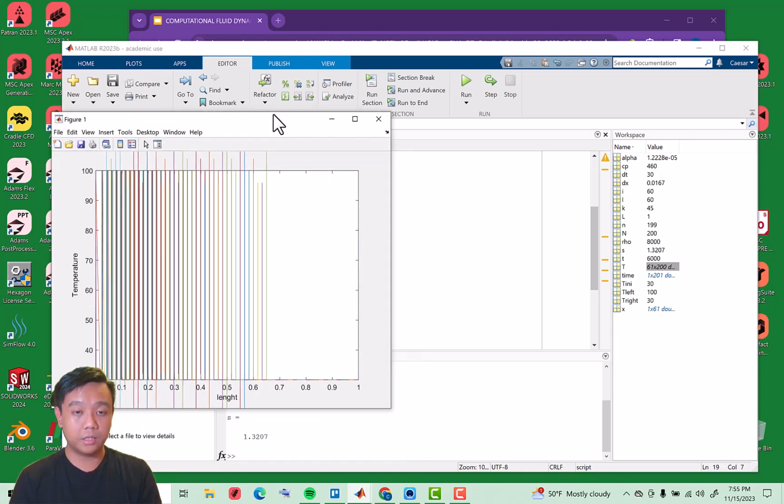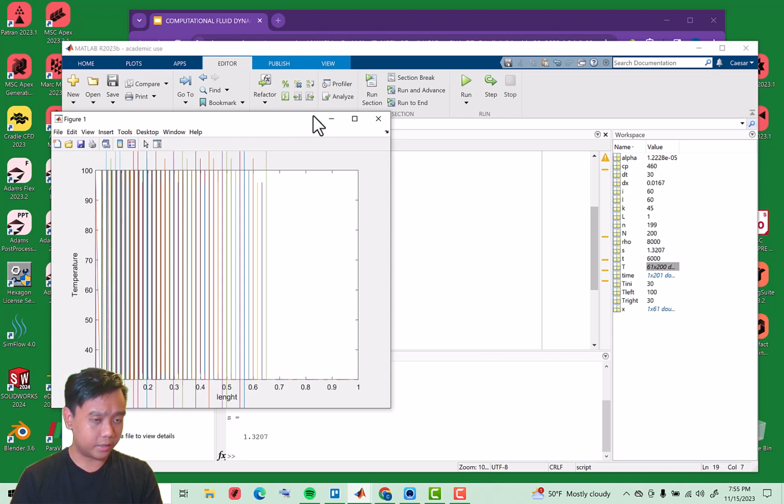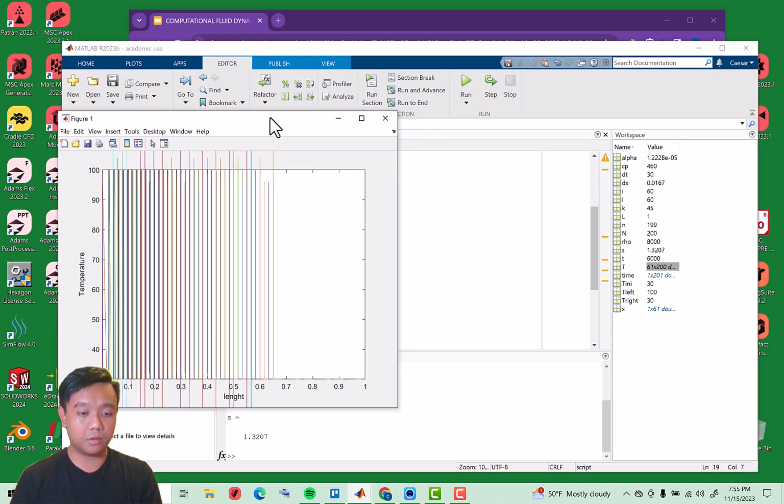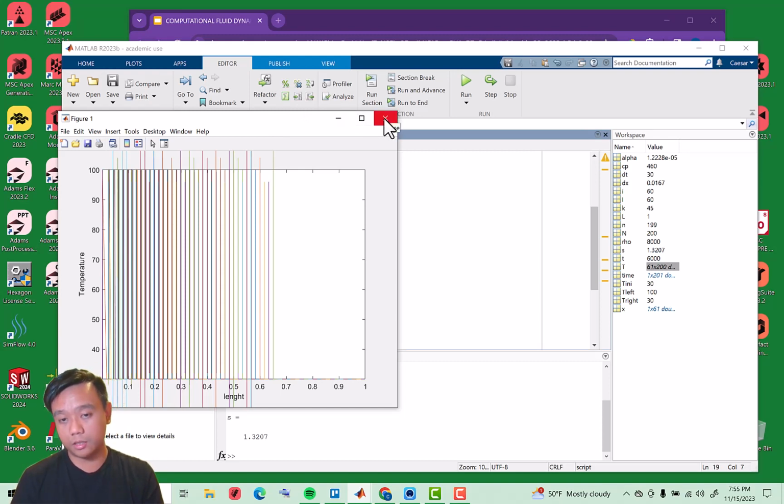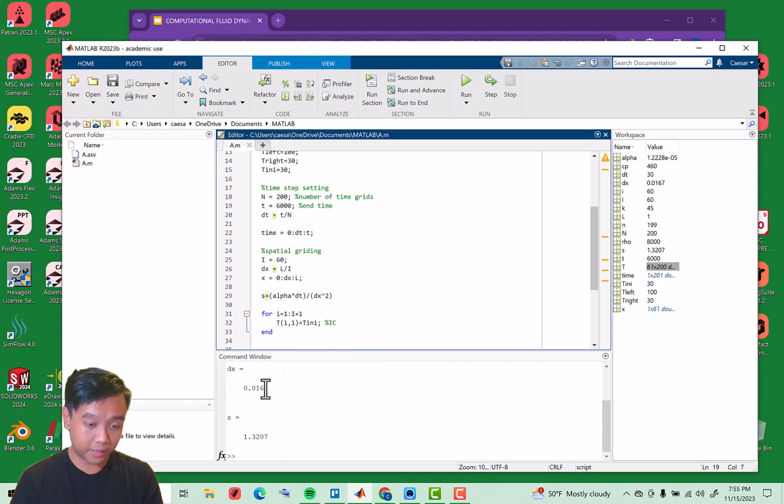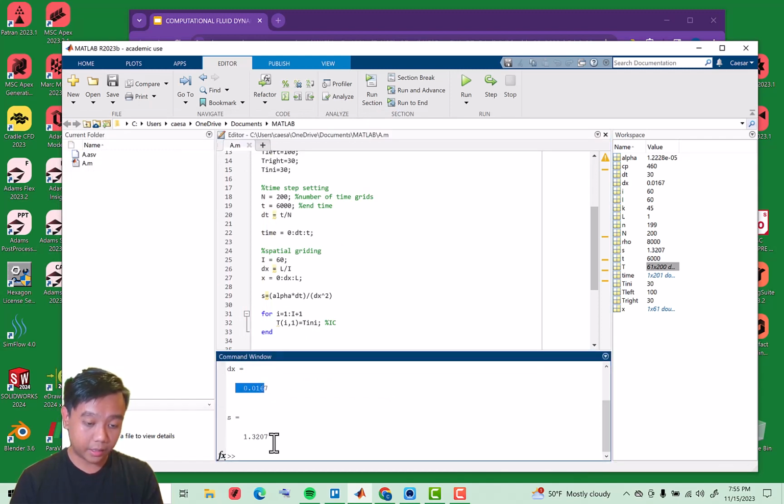So if we just input some values which are not correct, I can say, for the delta t and the delta x, the simulation will just blow up. And this is governed by the delta x, delta t, and the value of s. And we will discuss it later in our discussion about stability, and we will find what makes the simulation blow up. And this is actually a very important topic in numerical simulation, and I will make a dedicated video for that topic.